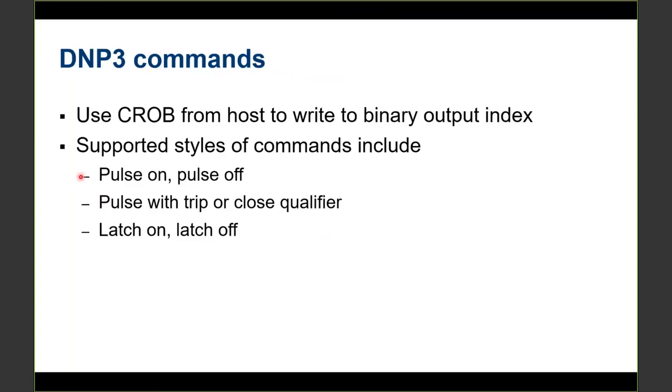Typically, this type of command is the most used in real applications, trip and close. But it is possible to use the latch on and latch off commands as well. In this case, it basically means the master station wants to put the output on the relay in latch on status or latch off. Pulse means just one pulse for a period of time.